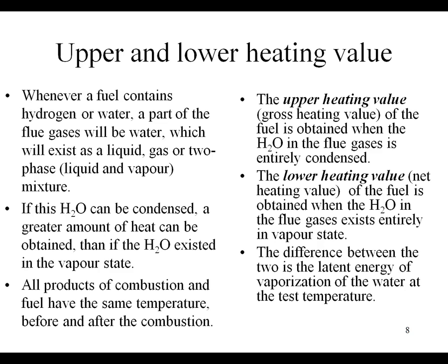And a part of heat is generated, but this heat you cannot use. It is not the real heat of combustion. It is a heat that you can use only in very special situations by using the condensate. Do you understand me? This condensate cannot normally be used. If it is used, it is okay. So normally, when you buy fuel for the company where you will work, you must look at the lower heating value.